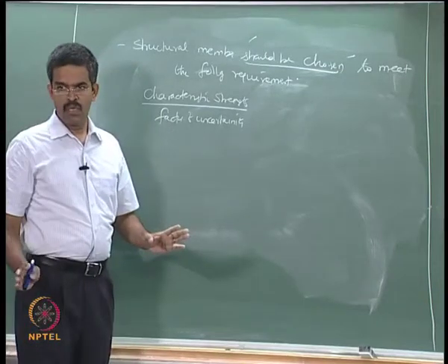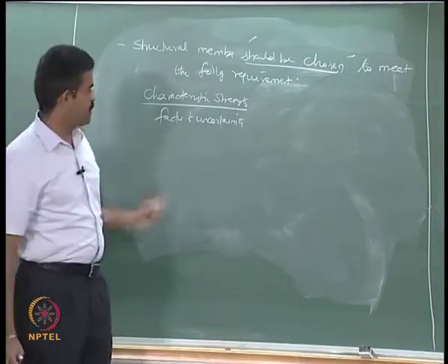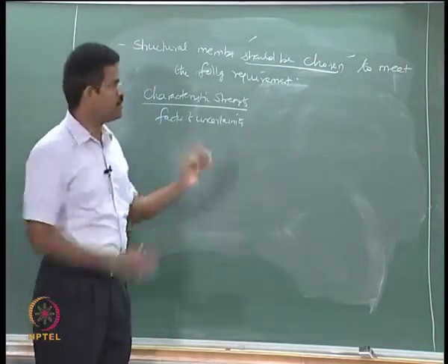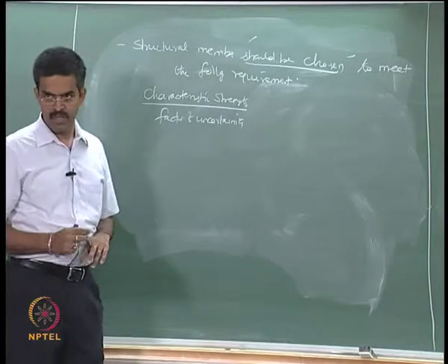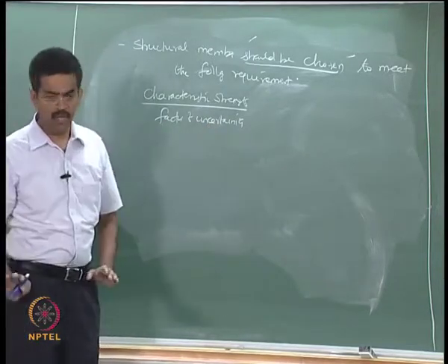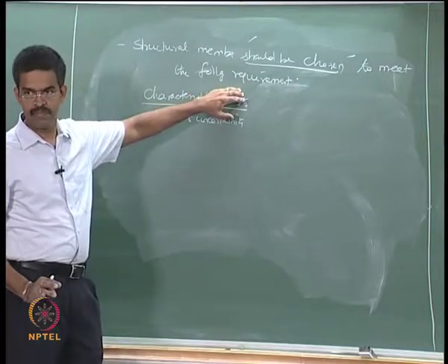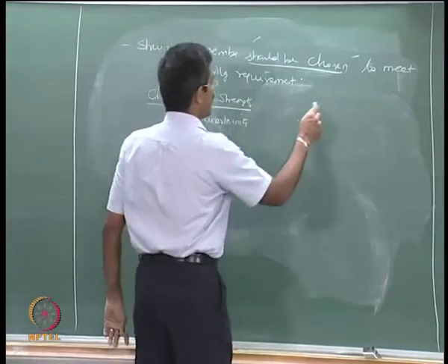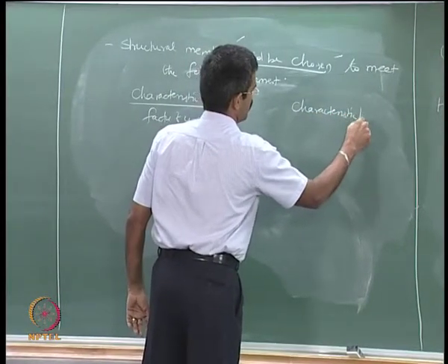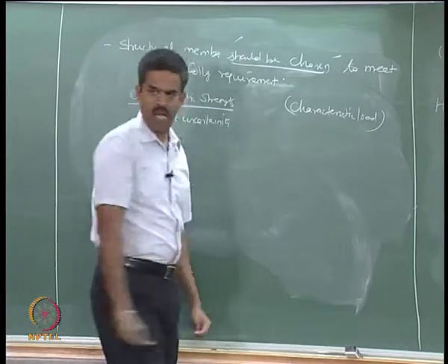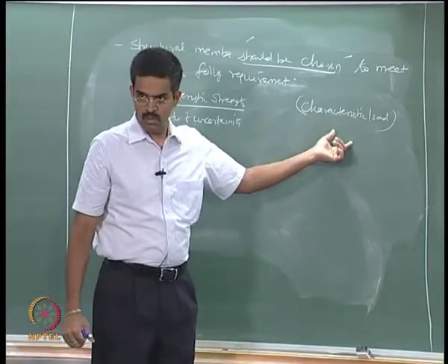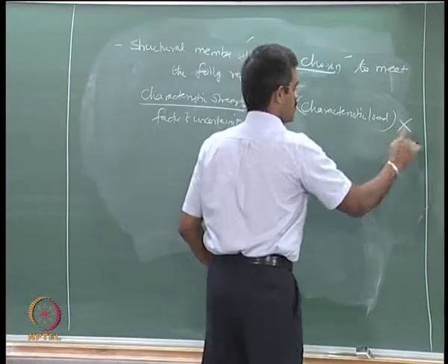So far I am not able to establish whether the system is safe, because for the system to remain safe I need to maintain a condition. This is factor of uncertainty which is independently applied only to the strength. Similarly, there will be a characteristic load which will also have a factor of uncertainty which is independently applied to the load, but in this case I will multiply this.